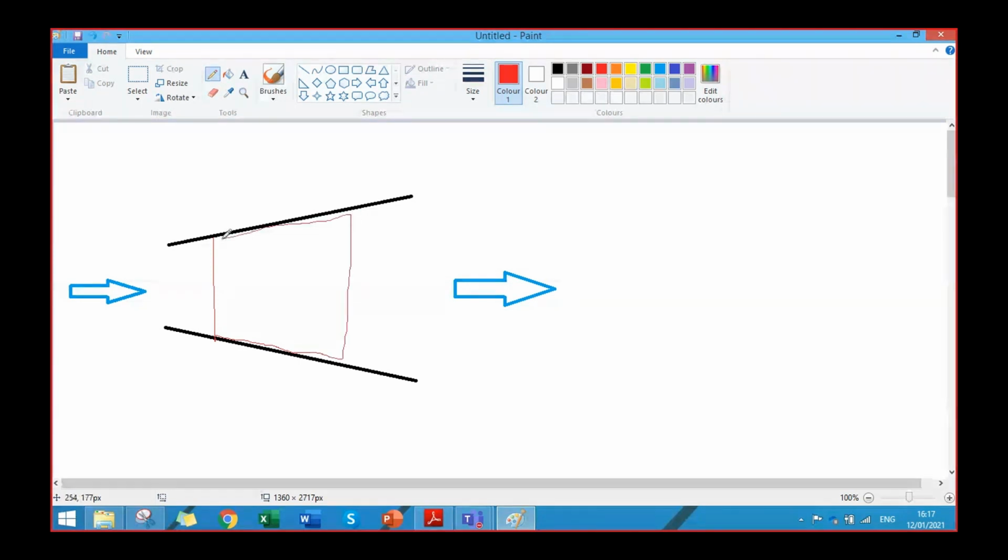I'm drawing it at t equals 0. At the same time, I am defining a control volume which is equivalent to this system. So the system and the control volume will be the same at t equals 0. So if I take any property B of the system, that should be equal to B of the control volume, right? At time t equals 0.